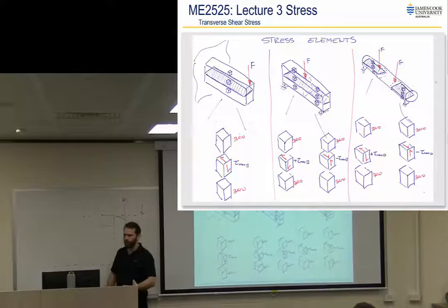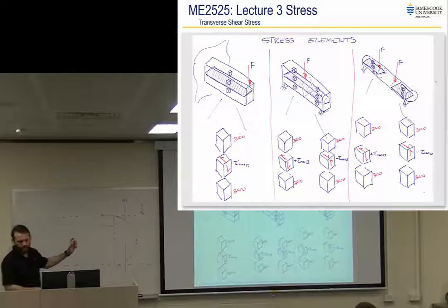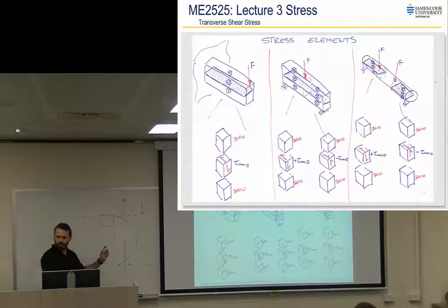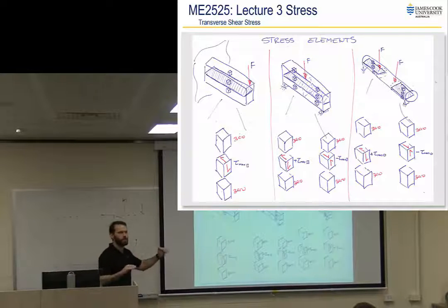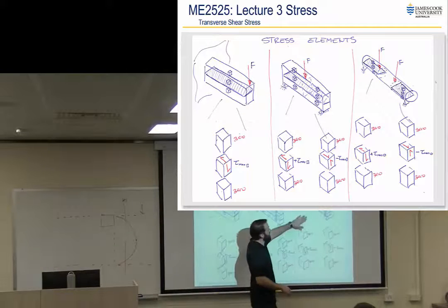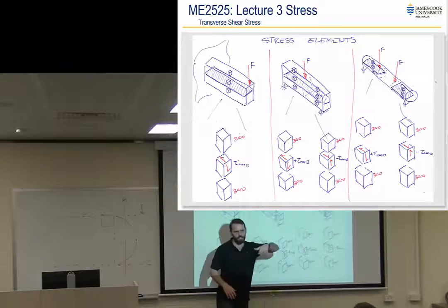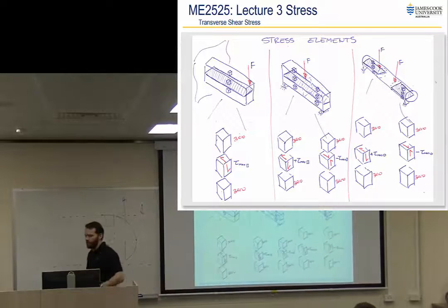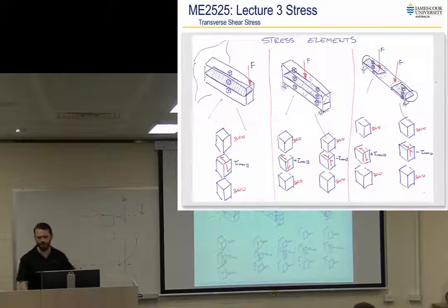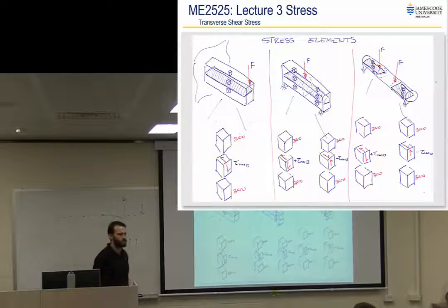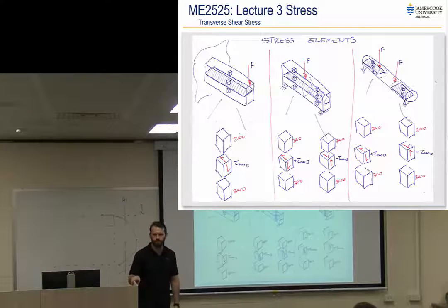Our last example, once again, we knew the left-hand end had max and the right-hand end had max anywhere in the center plane, because we've got a circular cross-section now, but it doesn't change, it's still that center neutral plane. And on the left-hand side, we had positives, and the right-hand side, we had negatives, and so we draw our shears accordingly. Cool? Make sense? Easy enough? Great. Let's do an example.